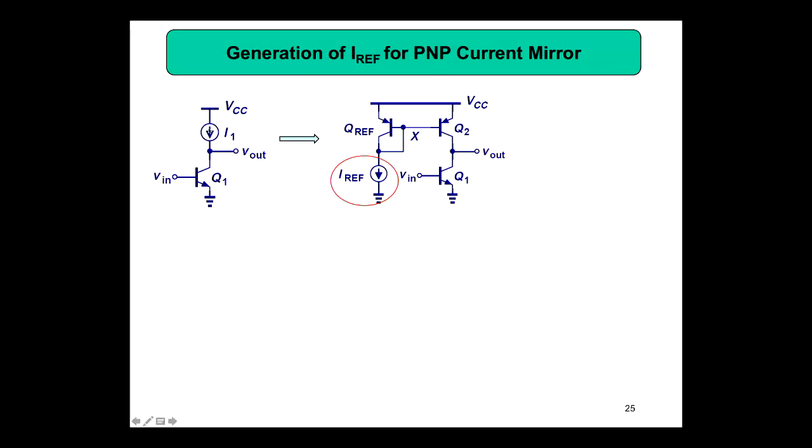When you design a current mirror, this is correct. So instead of this current source, you will be using a PNP. When you are using a PNP here, you have to use another PNP here, then only you can make a current mirror. So with another PNP, from the base you have to connect to the collector, then only you get the biasing. But the emitter you have to connect to the VCC. But then the problem is, here you have to connect your golden current. You know what I meant? So you got a band gap reference here, and can you connect your golden current to here?